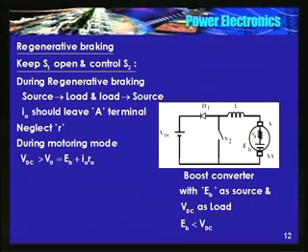Now see this figure, this is nothing but a boost chopper, a boost converter, wherein EB is the source, VDC is the load, and the condition should be VDC should be higher than EB. Output voltage V0 is always higher than the source voltage for the boost converter to work satisfactorily. Same thing is true here.